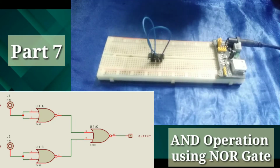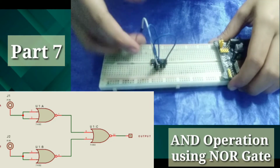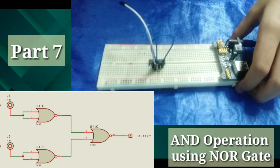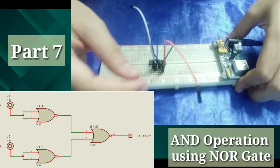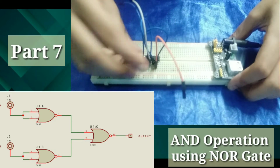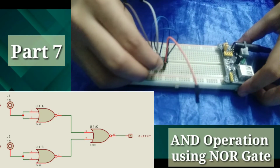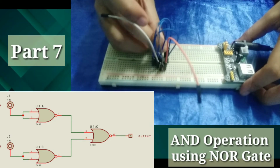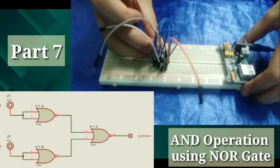Then, yung dalawa nating inputs, input A is connected sa connection ng pin number 2 and 3, and input B is connected sa connection ng pin number 5 and 6. Pin number 1 is connected to pin number 8 dito sa kabila. Pin number 4, which is ito, connected siya sa pin number 9 dito sa kabila. Then our output will be in pin number 10.